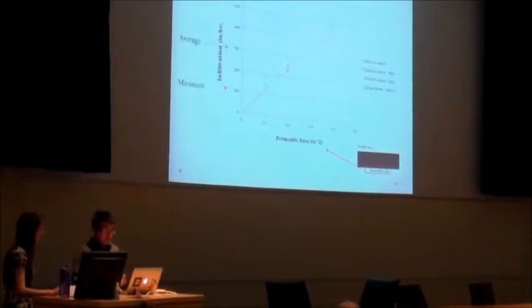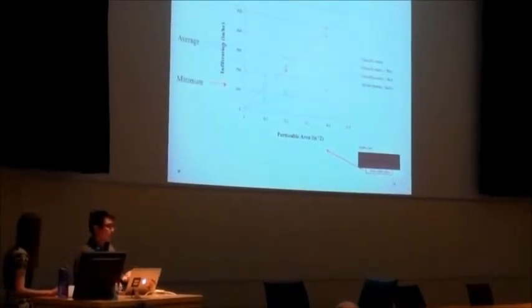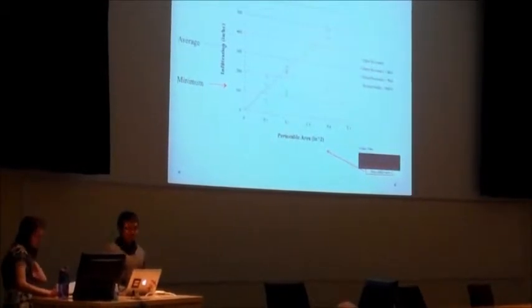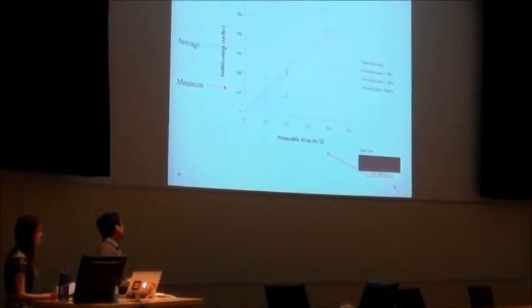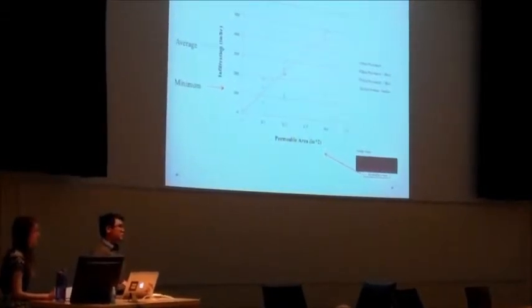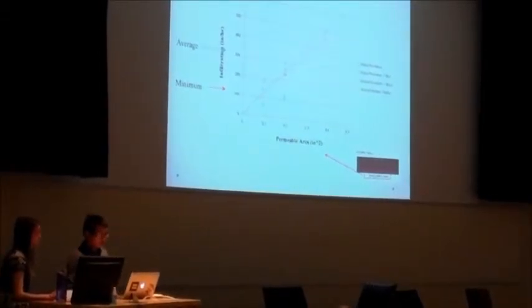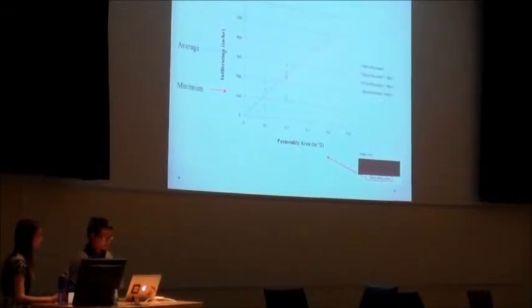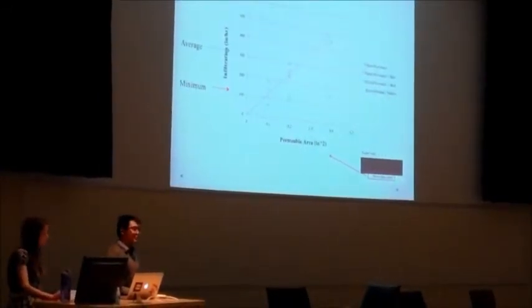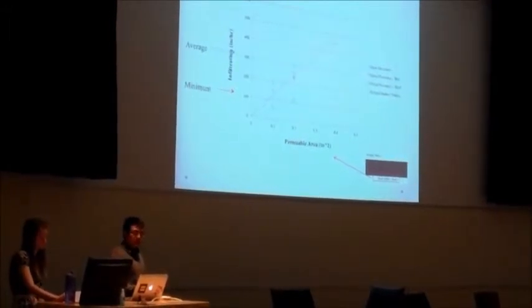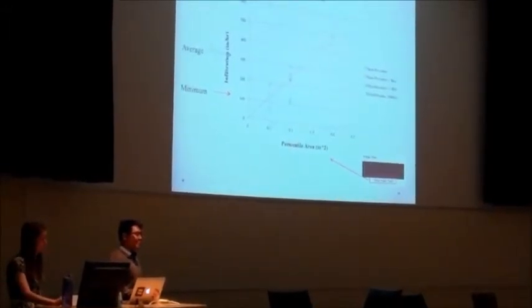Now, the last set of tests that we did involved filling these drainage pathways with filtration material. We just used pea gravel, but as you can see, it really restricted the flow rate through our concrete. And this might be an issue because for safety reasons, contractors may right off the bat want to fill these drainage pathways with material.